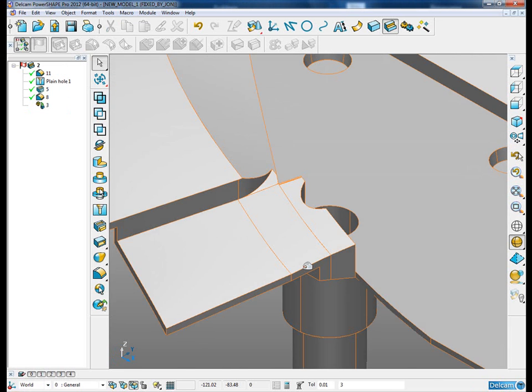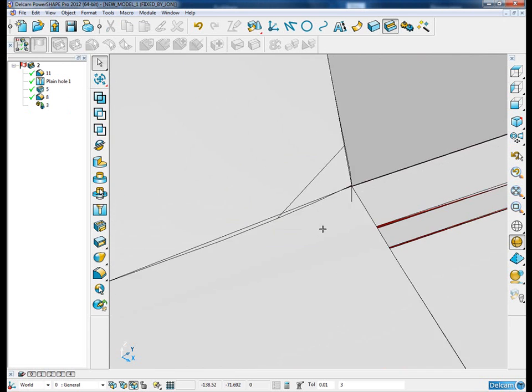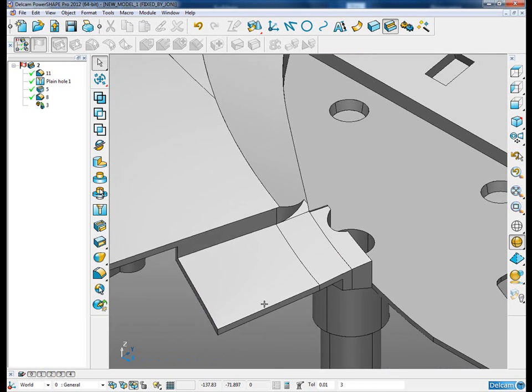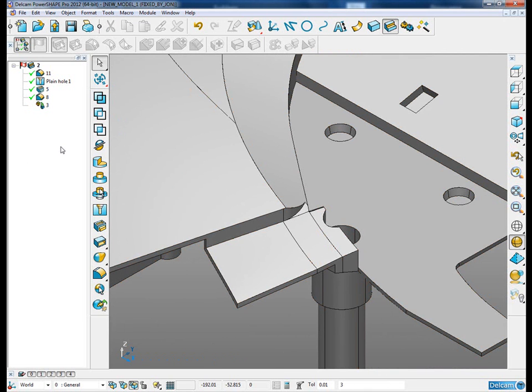So we mentioned earlier there were several faults in the model. Now the problem is, if I start pulling surfaces from the model or doing direct modeling changes, I am very likely to lose the history tree. Obviously sometimes you may want to keep this history tree. So let's look at a way we could work where we can keep the history tree and still perform edits like direct modeling and removing surfaces from the solid.